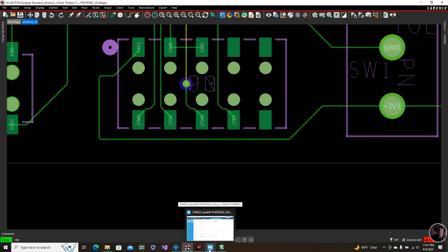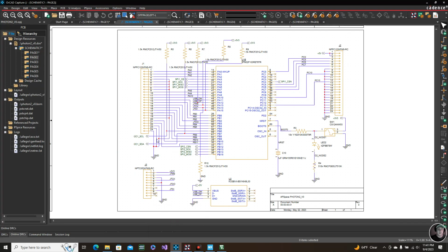The other thing to note is that when you're creating something that can actually be programmed, and if you're making a custom piece of hardware, you need a pull down resistor that's a 1.5K on JTCK, and then you need a pull up resistor on your JTMS and your JTDI. So this is a verified piece of hardware that can be programmed successfully with these pull-up resistor values and these pull-down resistor values. So if you have any questions of verification, this has been done on real hardware. So this is how you do the external pull-up resistor so that everything can be programmed.